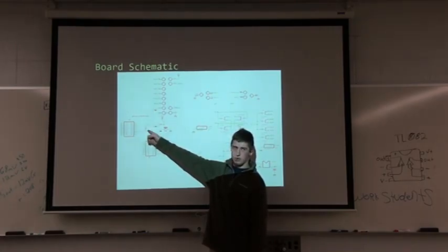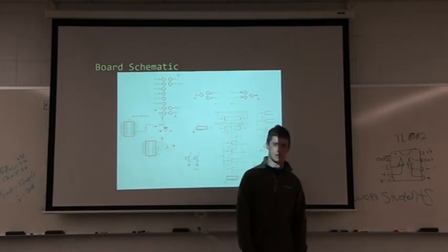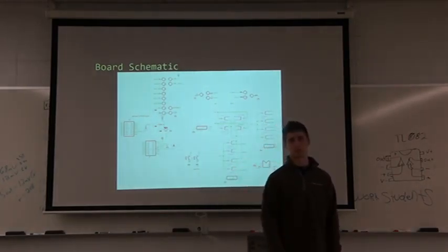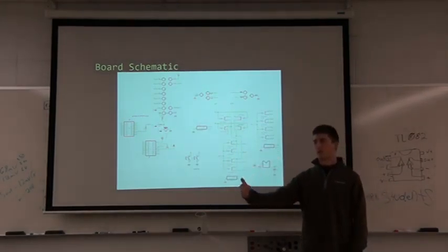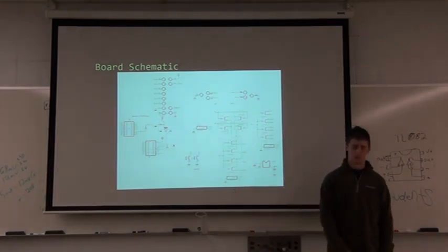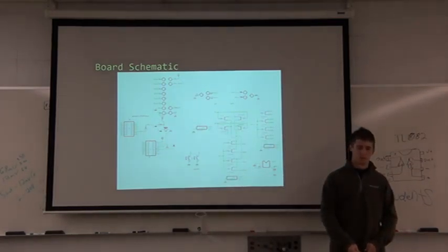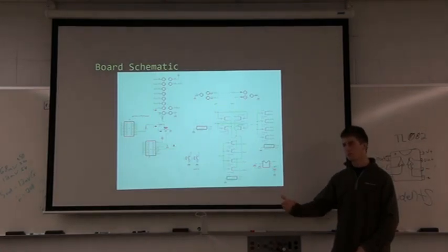The only thing that I really need to do some calculations for is for the resistor on the comparator input. The input to the comparator can't be too great because the reverse bias current cannot be greater than the specification in the data sheet. At this moment, I cannot recall what that specification was, but it was in the milliamp range.